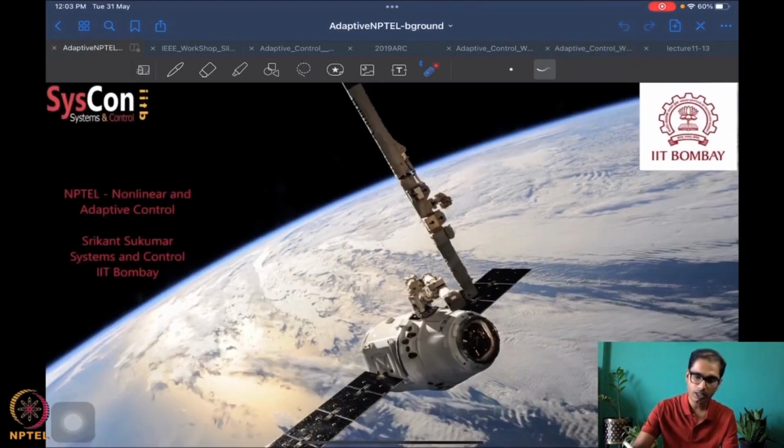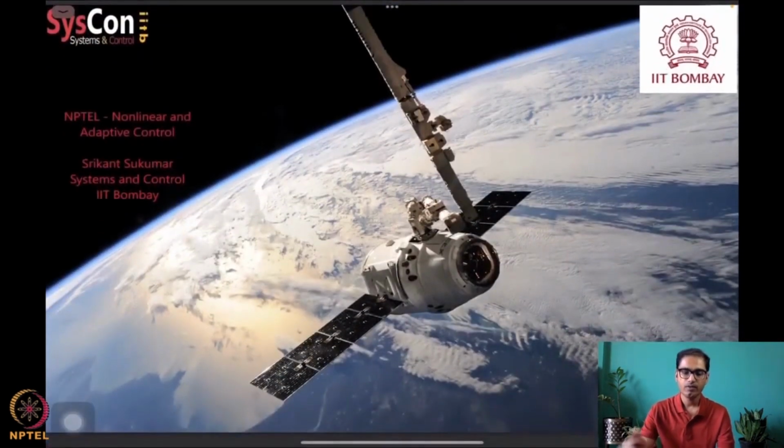Excellent. So what have we discussed today? We started with our discussion of ACLF, an adaptive control Lyapunov function, and how it is equivalent to having a control Lyapunov function for a modified system. And we also proved that having this control Lyapunov function for a modified system means that for the original system, we have an adaptive asymptotic stability property.